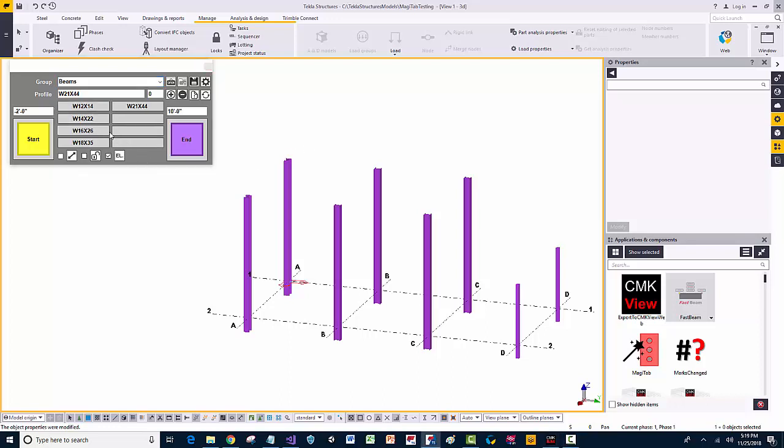Now once you change any of these profiles, just press the Save button so that those profiles are saved with that particular group. Now, in this particular case, I may actually want to set a default top of steel elevation for this group of beams. This is also why you might have a second floor, third floor, roof, etc. So let's go ahead and just type in 10 foot on both the start and the end point, and then I'll just press save again.